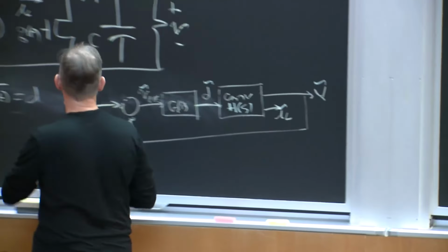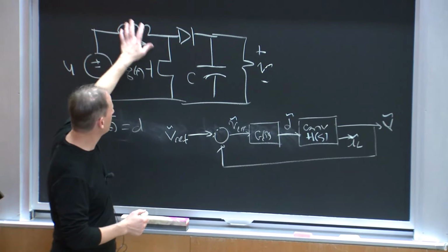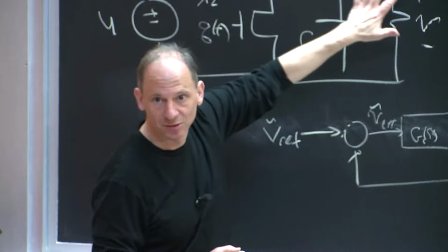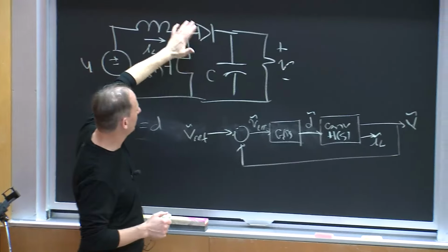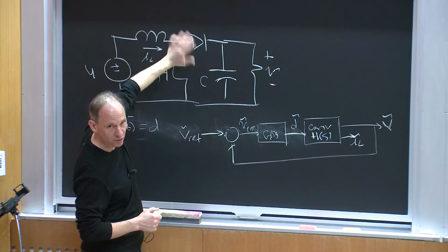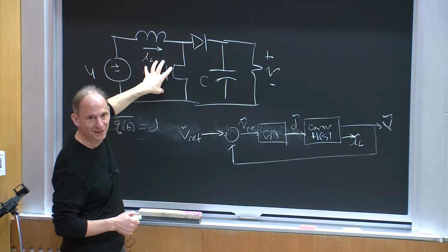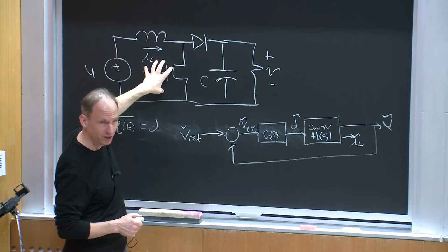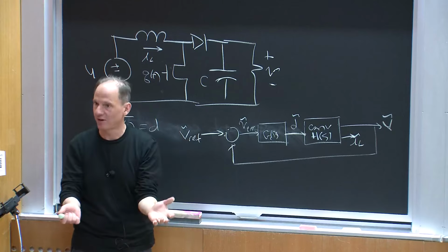The nonlinearity is there because what we're seeing is second order responses, some kind of oscillations between the inductor and the capacitor, damped by the load resistor. And those oscillations are mediated through the switching or the modulation of the switches, which varies with time. And more to the point, the steady state value of that varies with the DC input to output voltage, and hence the dynamics vary.